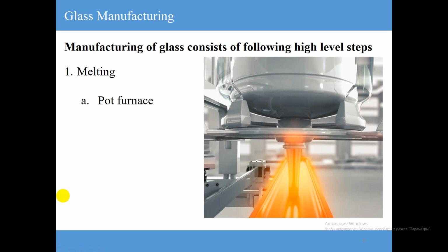The raw materials that float glass is made up of are silica sand, sodium oxide from soda ash, calcium oxide from limestone or dolomite, and feldspar. The above raw material, primarily mixed in a batch, helps to make clear glass. If certain metal oxides are mixed into this batch, they impart colors to the glass, giving it a body tint.